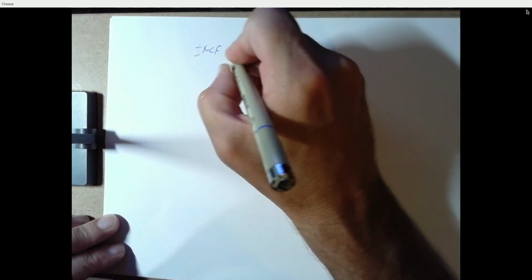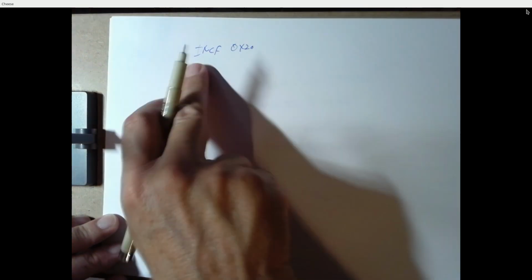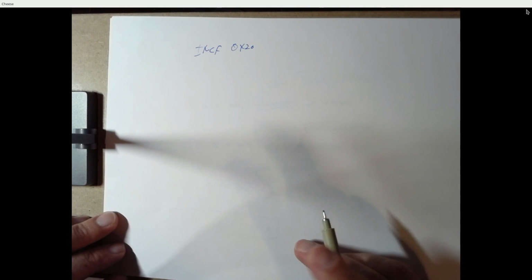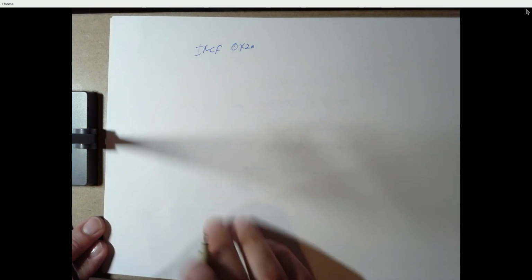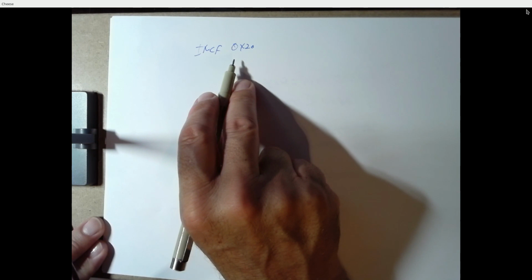So we want to look at how we take these assembly language instructions and translate them into binary, into machine code. Because we can say something like increment file register hex 20, and that means something to us, but to the actual hardware, the actual PIC processor, these ASCII codes are way too complex for it to know what to do. It needs very simple ones and zeros to be able to perform its decode and execute steps after it's fetched an instruction. So in program memory, we're going to store a series of 16-bit words, each word generally specifying one of these assembly language instructions. So we need to know how to translate from assembly language into binary, into machine code.